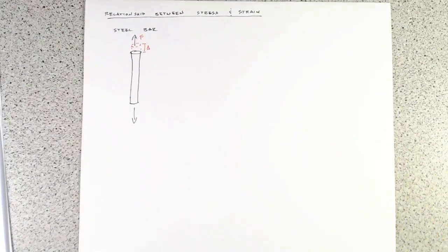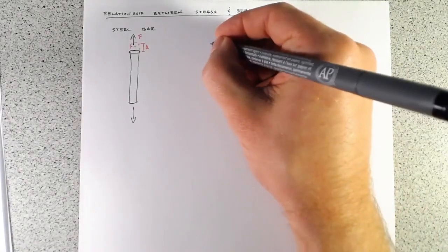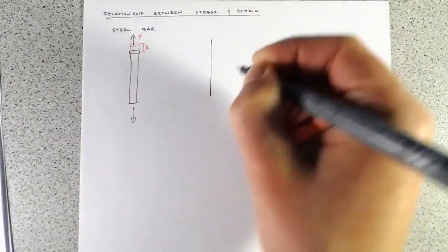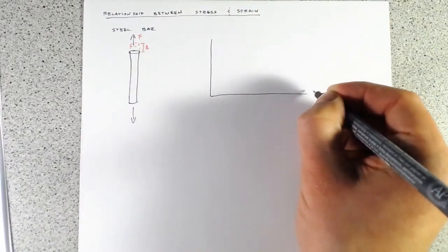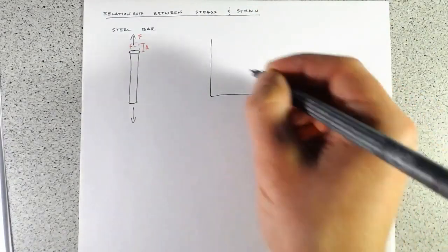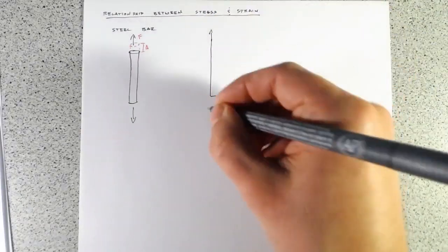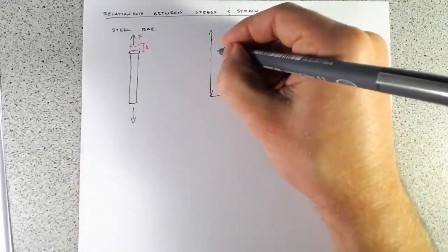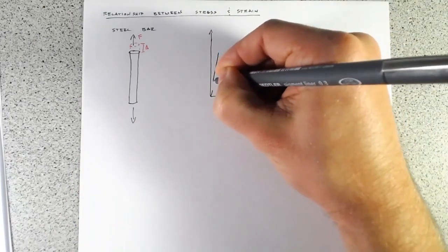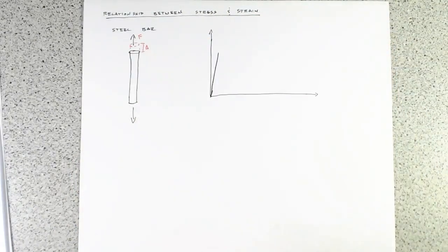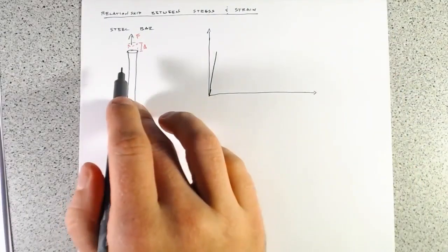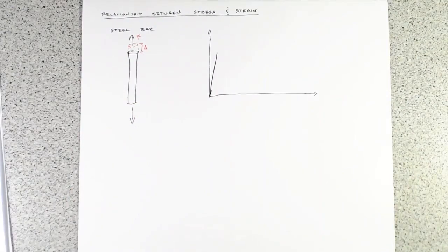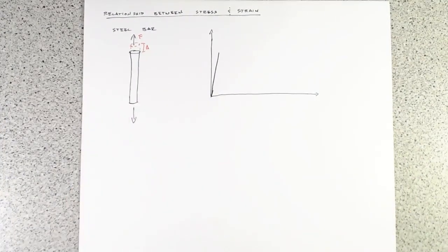And this is kind of what the force displacement plot looks like if we pull a steel bar in tension. So first, we'll pull it, and as we pull, we apply more force. We have this nice sort of linear behavior until we reach the yield capacity of the steel bar, and it yields.